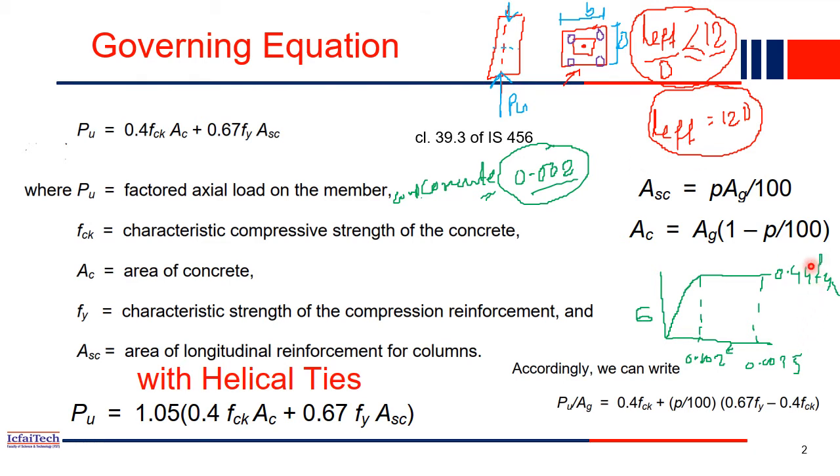But what we considered here is that even if the load is acting in a small area, we consider it an axially loaded member. In reality, you will always have some eccentricity in a member. Because of eccentricity, the strength of concrete will be reduced, since additional bending moment will be developed in the structure.